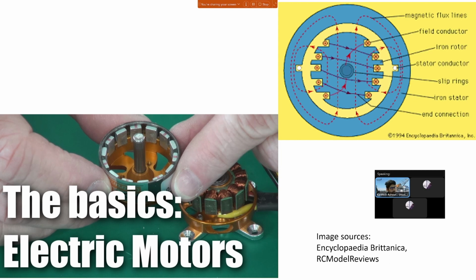This limits the power, but it enables a lot of simplicity because now you don't need any slip rings, no brushes, there is no DC excitation needed. So it simplifies a lot of the parts. That's why small model aircraft use these motors. But nowadays these motors are being used more and more commonly as magnets have improved a lot in recent times. Earlier there were not good strong permanent magnets, but now there are. So even, I think, wind turbines which make megawatts are using this technology with permanent magnet excitation.